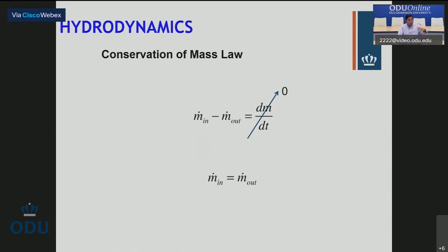Like if you eat 10 burgers, those 10 burgers got to go out. It doesn't matter how, but they have to get out of your system. Otherwise, you gain weight. In our fluid mechanics, we're assuming we're not gaining weight, neither losing. Now, this is a long conversation, just because I need you to learn what m dot is, and I need you to learn that mass never changes. That mass flow rate never changes.